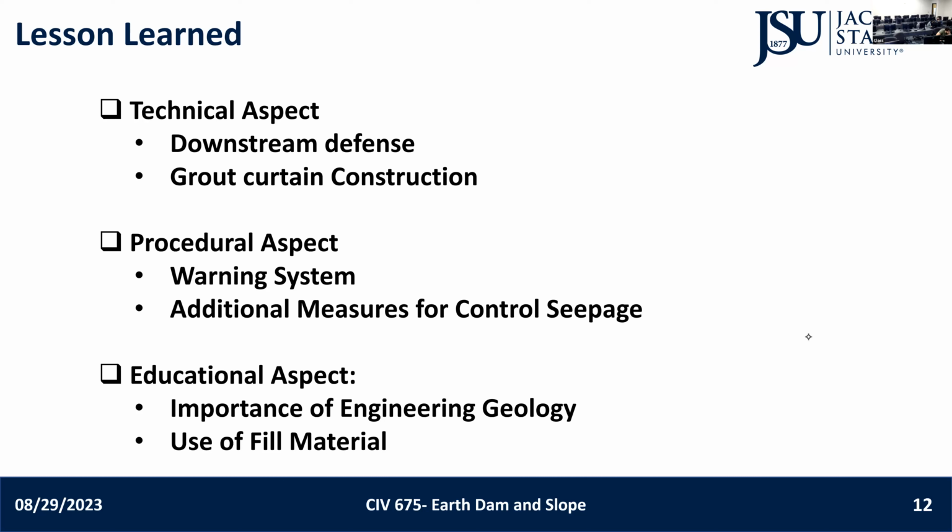And the filling material was really low quality. How do you define low quality filling material? It was permeable actually. Okay, very good. So what went wrong? Piping happened. Internal erosion. So this is the major failure because of the piping, right? It is one of the major failures according to the report. Basically, it's a piping failure. And another detailed study said there was flow beneath the foundation.